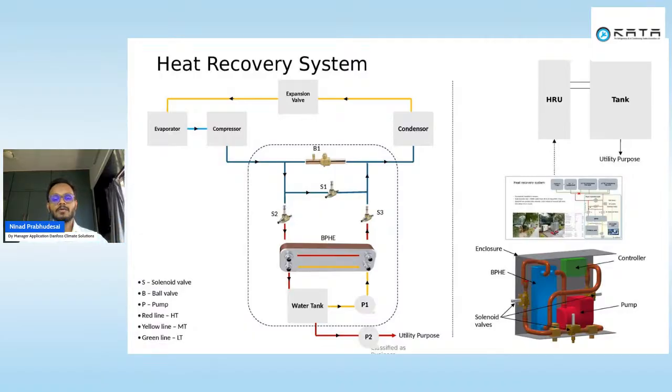There are two major advantages. One is that the heat of the gas is anyway being rejected in the condenser, so your condenser is getting loaded because of the high temperature inlet gas. And the second thing is, this energy is free actually. We are simply going to reject it into the ambient, so instead we are consuming it here in the heat recovery unit, and using that energy to heat some water or brine, whatever as per the requirement.